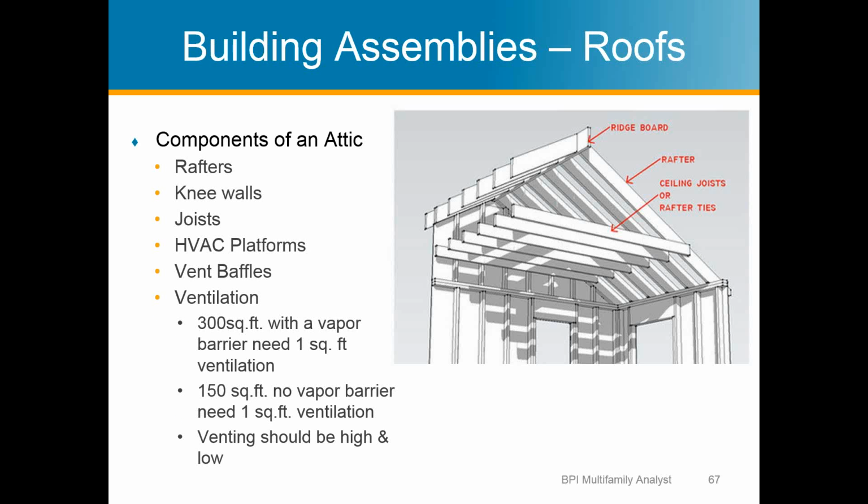So building assemblies, there's lots of different components to the roof, as in everything, and I've used a lot of terms in this, like studs, sill plates, king studs, trimmers. Those terms we're not going to go over, but you should know for the exams. Know what a rim joist is. Those are just some basic framing terms that you should use. Sill plate, top plate, know what those are. And this picture shows a few of them.